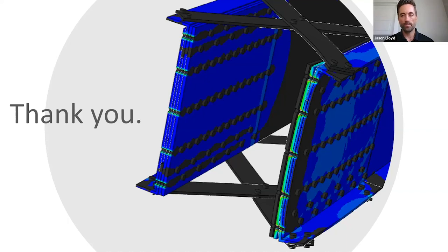Yeah, the guide specification for system redundant members goes into detail. It doesn't list specific products necessarily, but it will give some guidance on the capabilities that the software needs to have, including things like nonlinear material and nonlinear geometry. You get into shear stud behavior, concrete crushing, some of those more refined steps in the analysis. So as long as the software is capable of that level of analysis, then it should do fine.